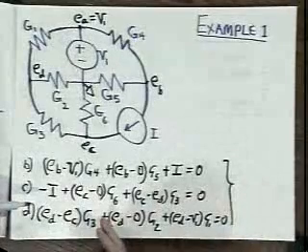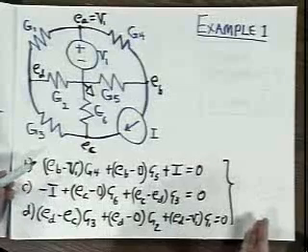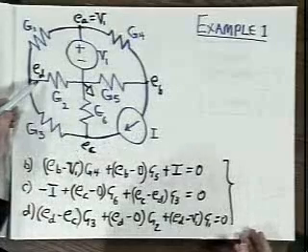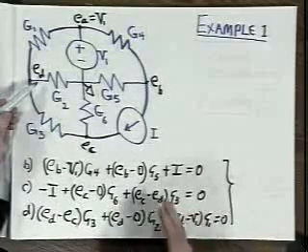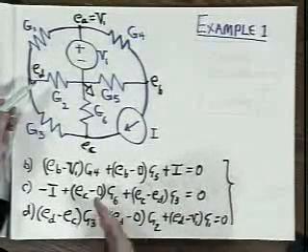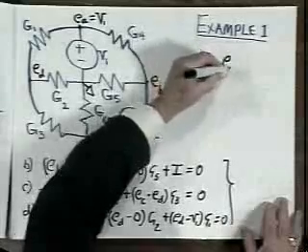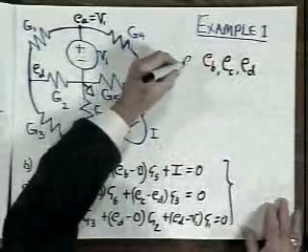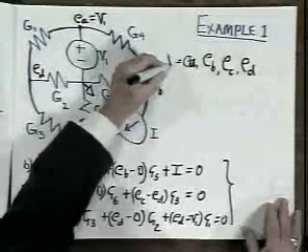They are all expressions of Kirchhoff's current law, and they amount to 3 linear equations in 3 variables. The variables being E sub B, E sub C, and E sub D. Those are the 3 unknowns in these 3 equations, and from here on it's just algebra. You turn the crank on a 3x3 matrix and solve for the node voltages E sub B, E sub C, and E sub D. You already know E sub A. E sub A, that's equal to V1.